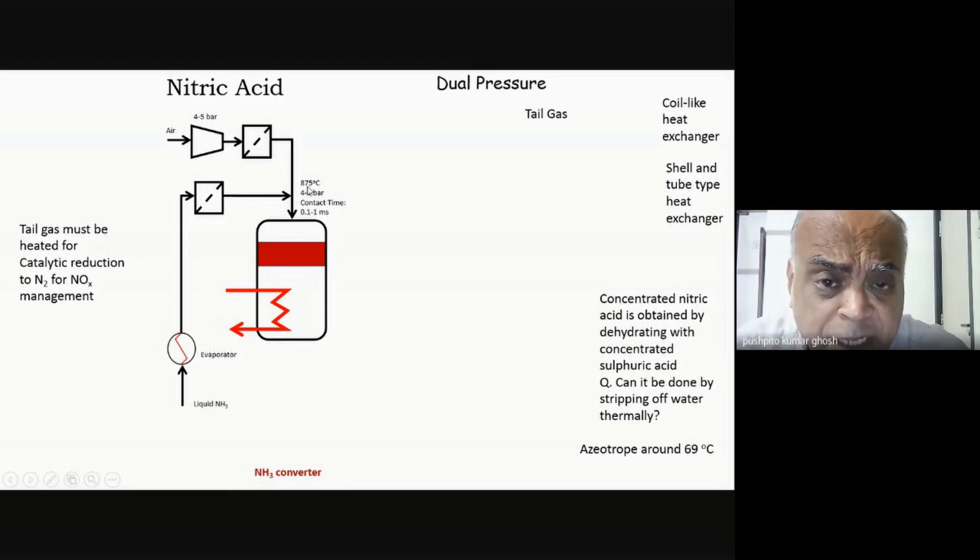As I said, the high temperature was not only for the high rate of the reaction, but to have substantial differentiation with the undesired reactions, and we had discussed the undesired reactions, which can form nitrogen, for example, from ammonia. And so we don't want that to happen. And so presumably at this temperature, you get the highest differentiation in the rates of the two reactions, because it's all controlled by kinetics, in this case.